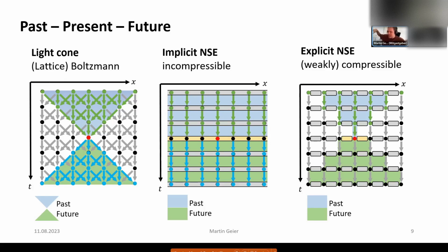So we take our spatial derivatives, which are usually on the right-hand side of the Navier-Stokes equation, and from this we compute a local time derivative, which, taking say a Runge-Kutta scheme, gives us the future of this next node.